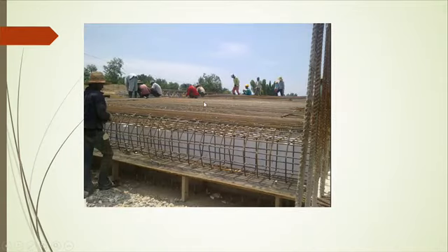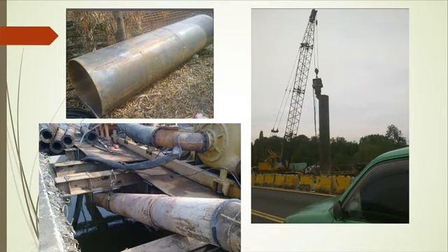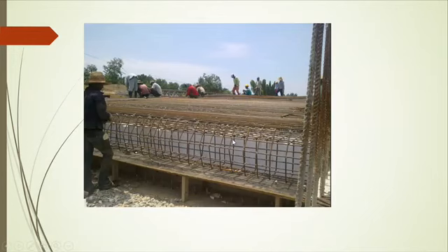As you can see, you need to arrange the bars according to the spacing, and then you have to have this amount of workers here. One group here just to arrange the steel bars, and one group here just to tie up the bars. So that is the duration they need to produce this. This is to produce a deck slab. This is the slab of the bridge.